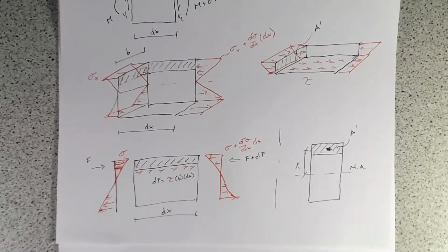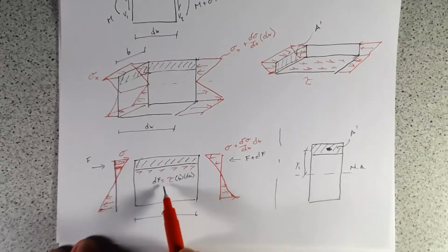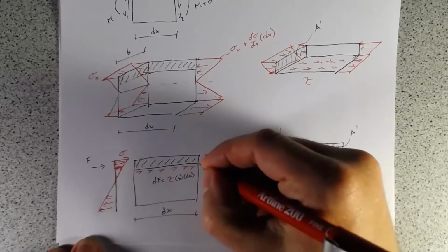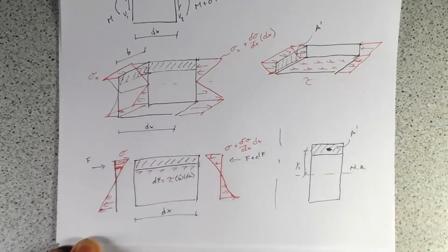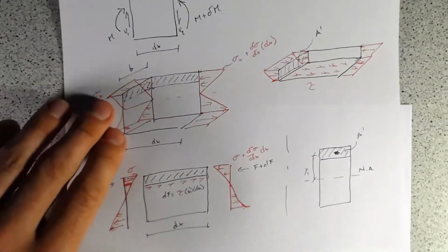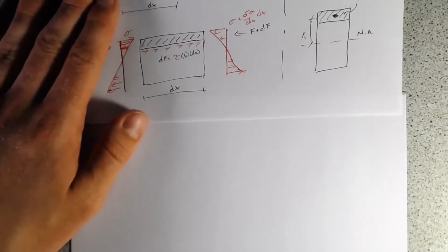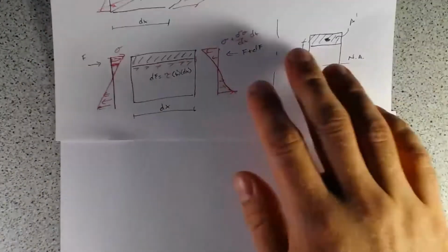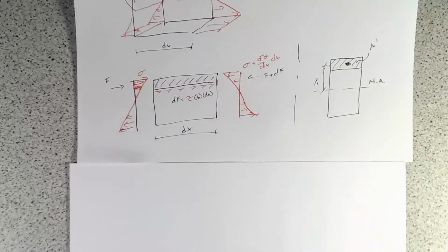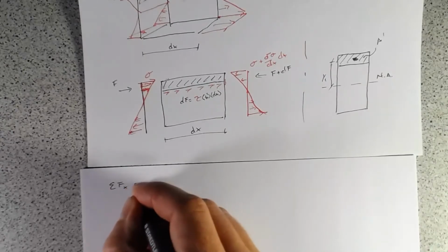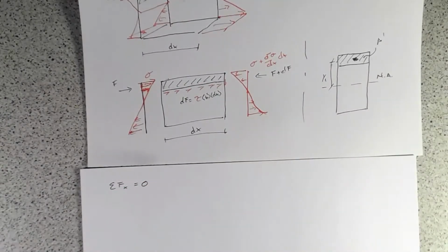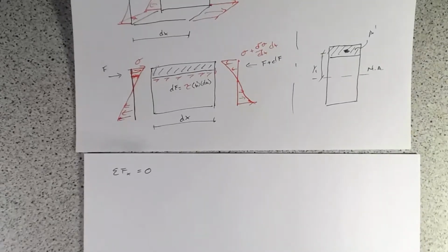That's our stress state. Now, in order to derive what our shear stress is, if we can find this shear stress, then we can find the shear stress right at the corner there, and we can do that going down the depth. So to do that, let's set up our equilibrium equations. Let's sum the forces in x and let that equal 0. And remember that, to get a force out of a stress, we need the stress over an area.